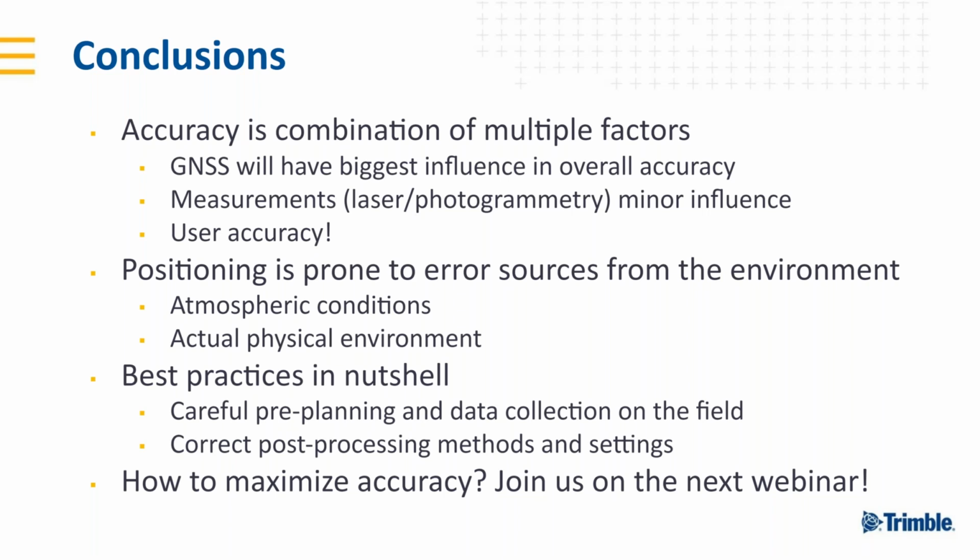If I put all the best practices we went over in a nutshell, I would say the first thing is careful pre-planning. If it's possible, get to know your data collection area beforehand and plan how you drive, where you do the initialization, and so on. Also be careful when you're collecting the data to monitor the PDOP, monitor the navigation solution, and do the necessary things when they need to be done. And then later in the office, use the correct post-processing method, use correct settings for your mission, and so on.